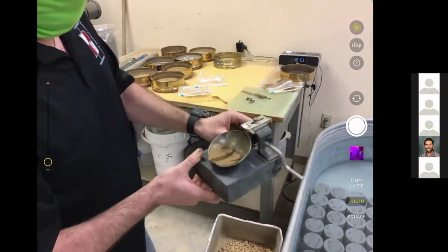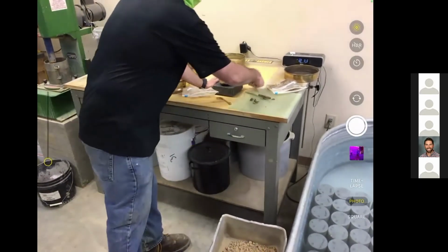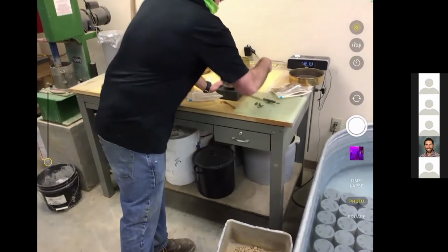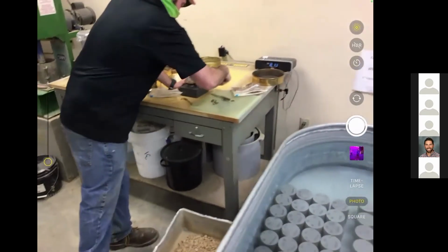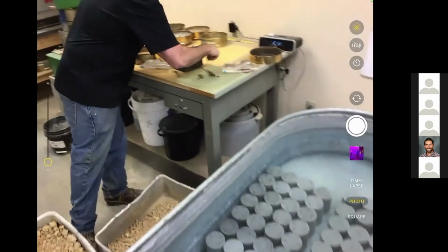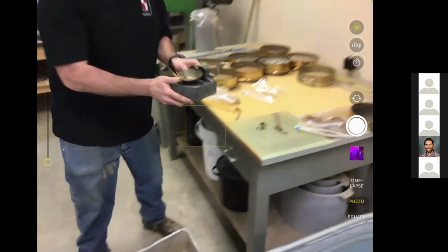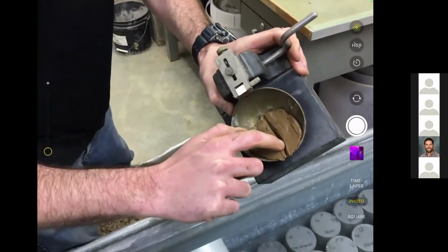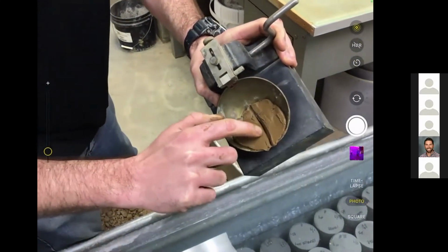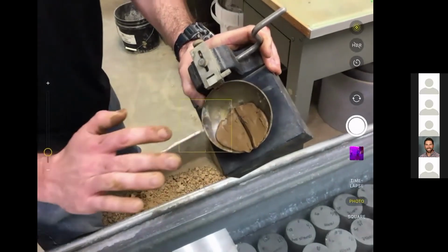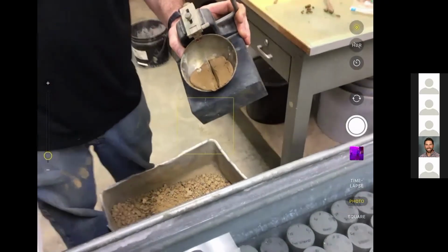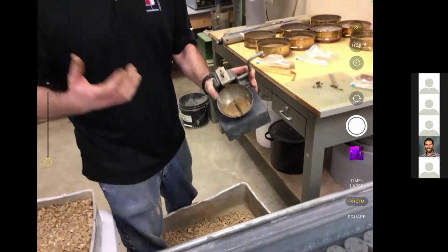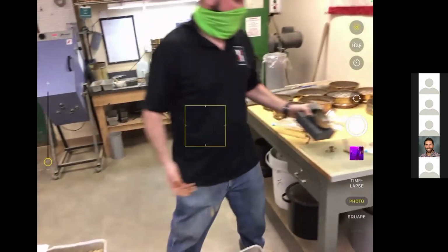So basically all you're going to do then is start counting. At the end, you're going to end up where the groove closes in on itself. At that point, that's your liquid limit. It's no longer a solid, it's starting to become a liquid. That's going to turn into your plasticity index.